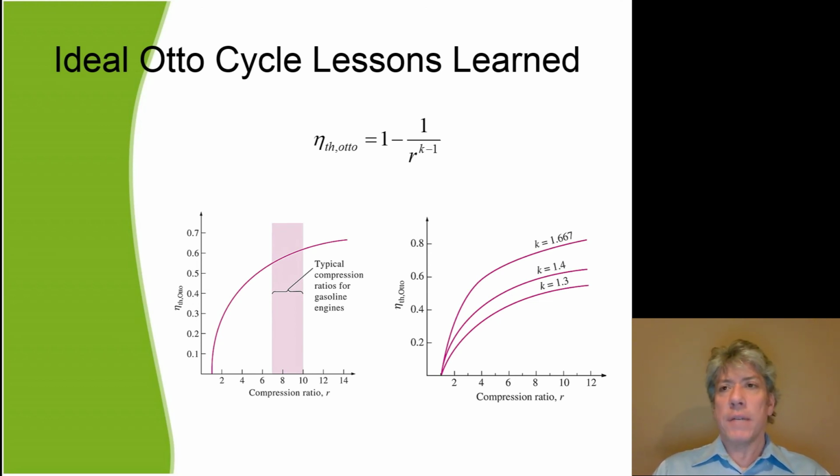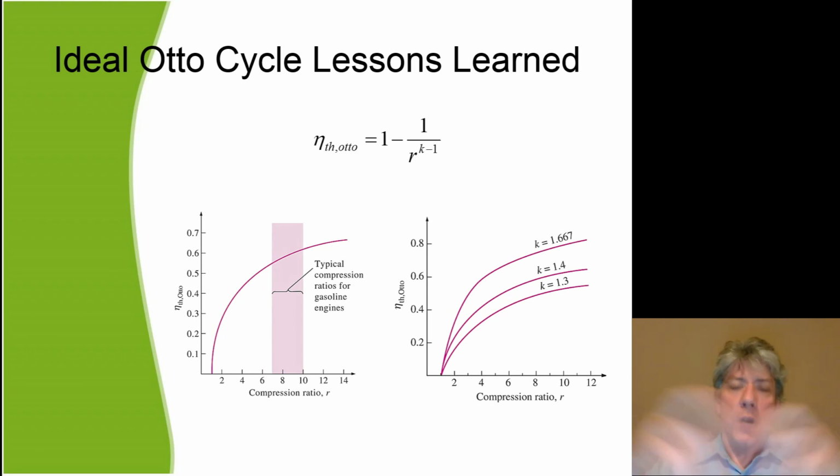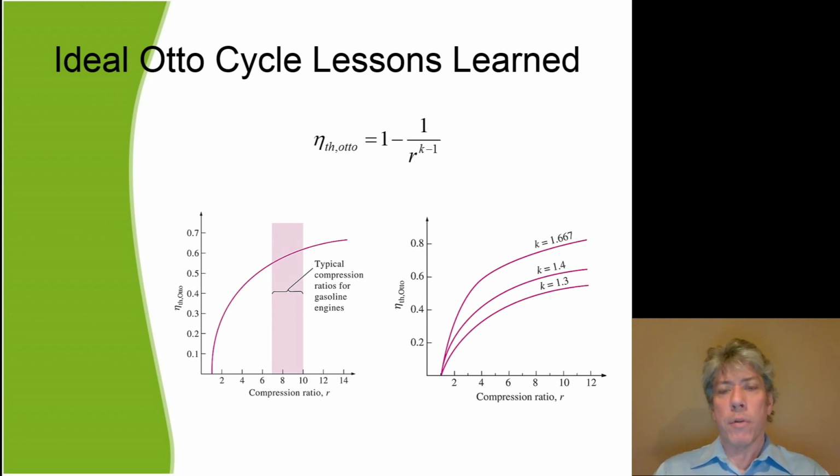Now you might say, well, I buy high octane fuel because it's got more energy and it's a better fuel. Actually, high octane fuel is more difficult to burn. The reason that it prevents detonation is because it's harder to burn. It's more of a closed form of molecule, and it's harder for oxygen to get to it. Basically, the oxygen has to burn away some of the fuel before it can attack the core and burn the remainder of the fuel. If you look at the octane rating on diesel, for example, it's a lot higher than even high-grade gasoline.